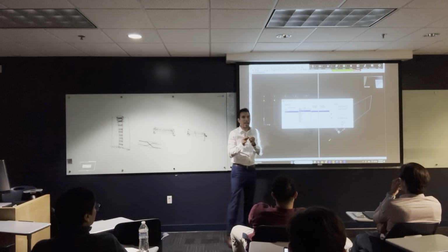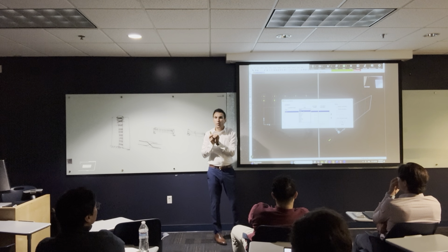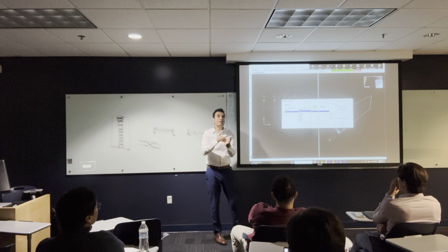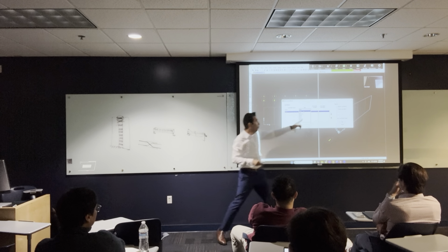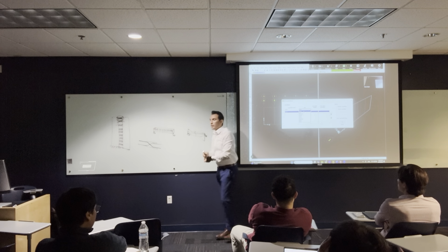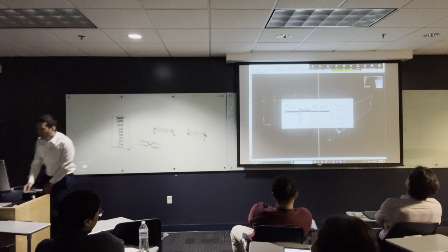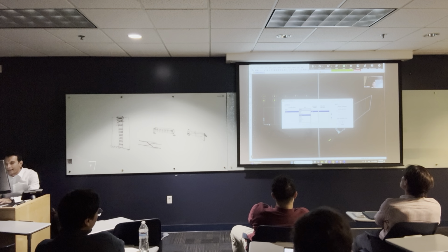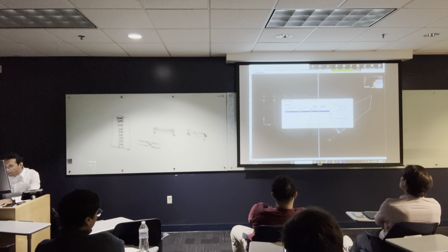So basically it asks you, how much of the self-weight of the structure do you want to save in this load case? If you put 1, that means you want 100% of the own weight to be saved in this load case. If you want to make it 0, you just keep this as 0. I'm going to say 0, and then I'm going to say modify load pattern.